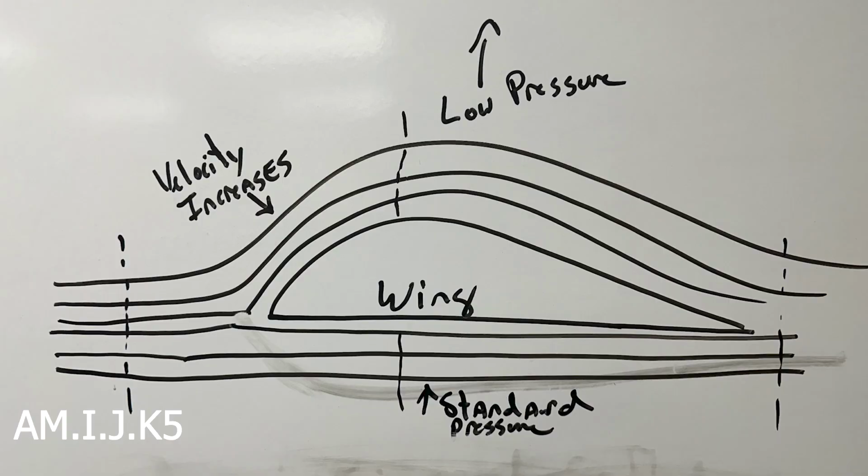In aviation, Bernoulli's principle is crucial for understanding various systems, such as the generation of lift on an airplane wing. The curved top surface of an airplane wing acts like the converging section of a Venturi. As air flows over the curved top surface, its velocity increases and static pressure decreases, creating a pressure difference between the top and bottom surfaces of the wing. This pressure difference generates lift, allowing the airplane to fly.